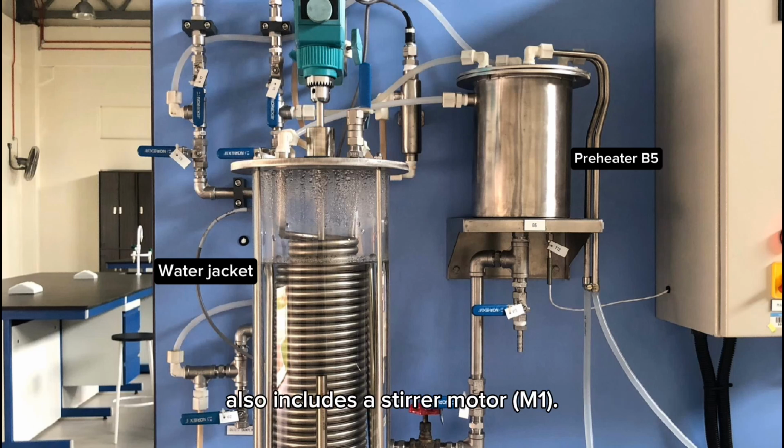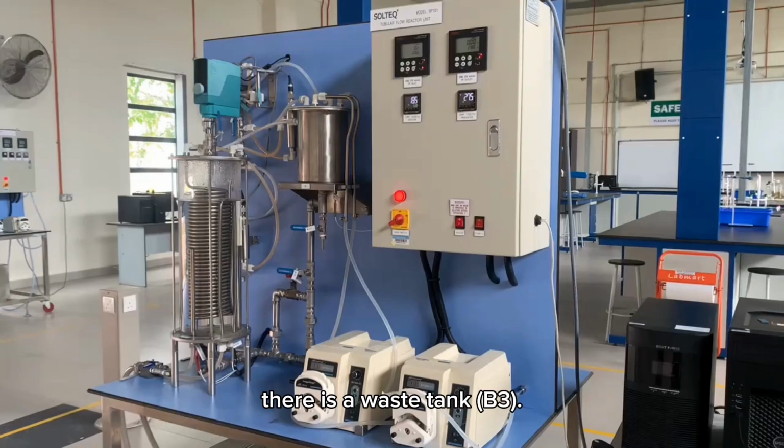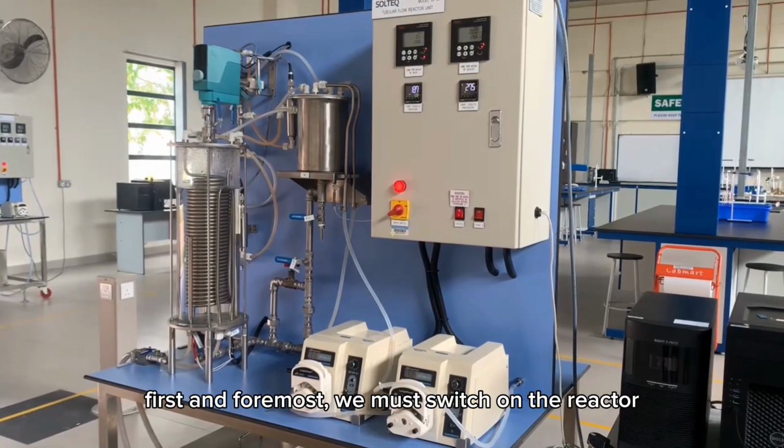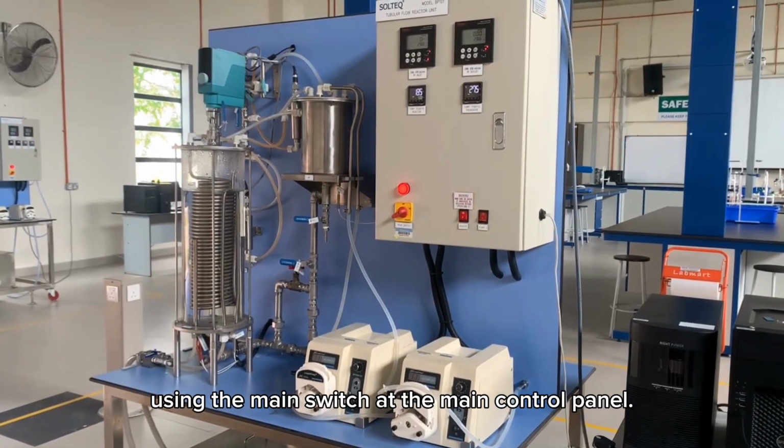This equipment also includes a stirrer motor M1. At the bottom pipe, there is a waste tank B3. Experiment for the plug flow reactor. First and foremost, we must switch on the reactor using the main switch at the main control panel.